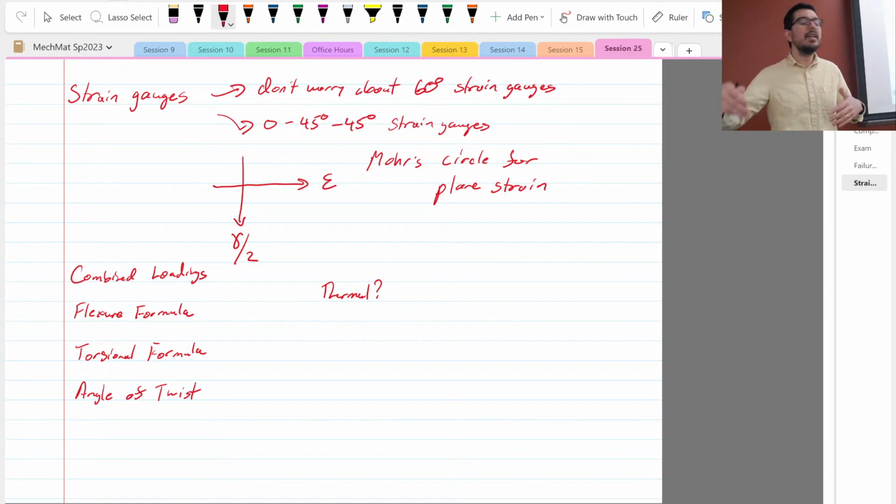Whereas aluminum is 70 gigapascals, steel is 200 gigapascals, right? For elastic modulus, think gigapascals. Yield strengths, or even ultimate strengths, either compressive or tensile, are in megapascals, and often hundreds of megapascals. Mohr circle, hundreds of megapascals, okay?